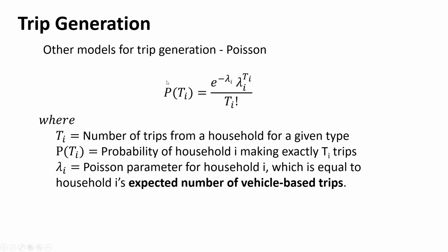So this is our standard Poisson setup. The Poisson equation should look fairly familiar. Lambda is usually the average value of something, whatever it is. T is our interval, and that's the number we're looking at in that interval. So for the probability of one vehicle arriving, one trip being generated during a certain time, we'd plug in 1 here, and we'd plug in 1 there. Lambda is the average, and E is the natural exponential function. So we can plug all that in and figure that out.